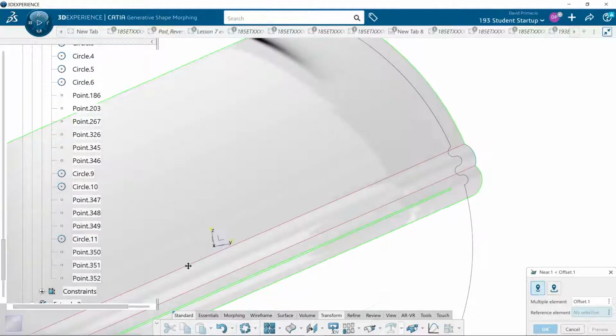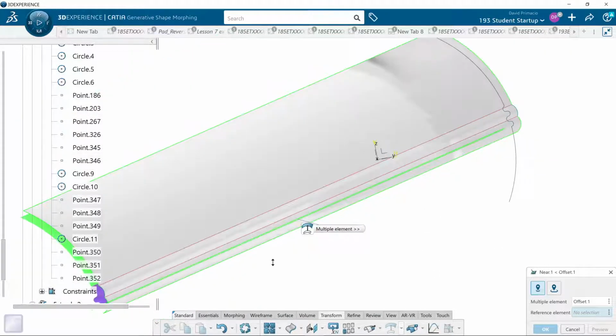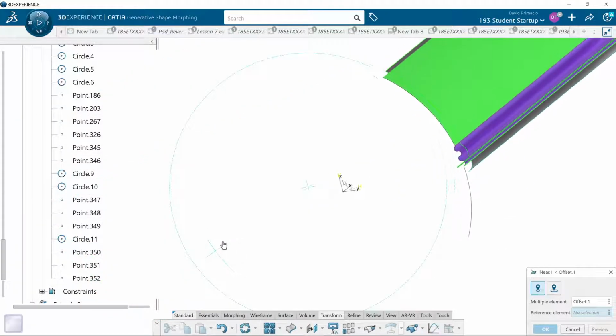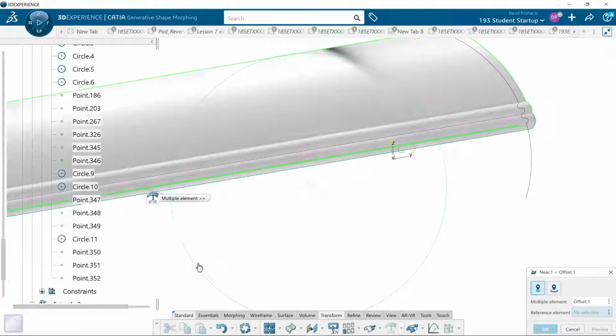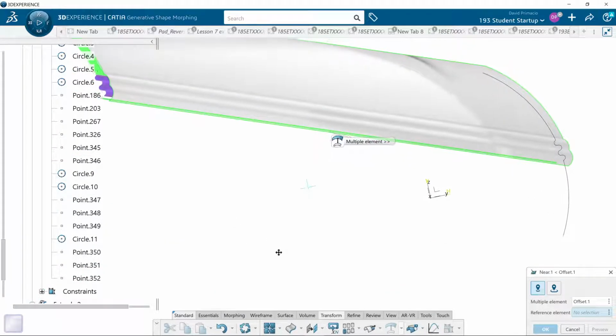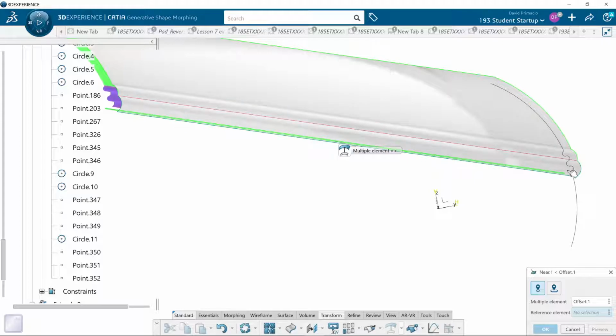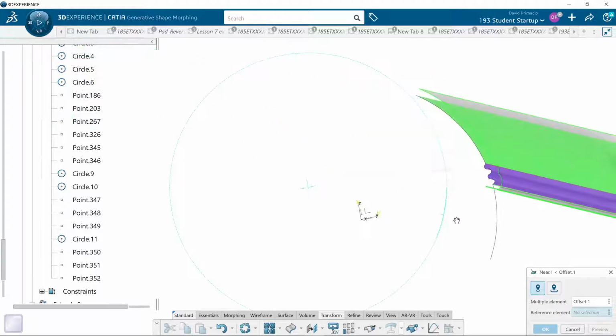Zero radius. Yeah, I'm getting that 0 radius. Remember I talked about that in the 193 class? When you offset, you can only go so far. Well, when you're looking at a big, huge surface, a 1/4 inch surface should be no problem, unless they got the points all screwed up. And then when I try and take their surface and offset it, I can't do it. I would have to break this into tons of little surfaces, recreate a surface that would work, and then offset it myself. It really shouldn't even be that way, because I'm now changing the integrity of the original engineering surface they gave me to get it to work so I can make my part.